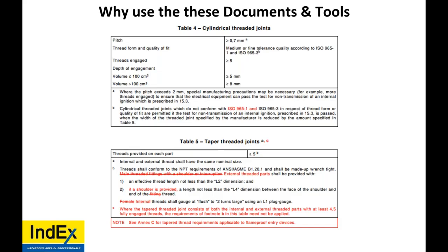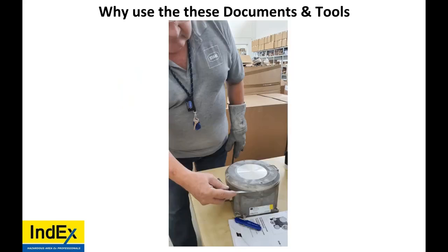If you don't tighten all the bolts correctly, if they're too loose, that's a problem. If it's too tight, you can damage the walls of the cover of the enclosure. You can warp it. This is a bomb-proof safe. We're using the feeler gauge there to make sure that the cover on this threaded type enclosure is sufficiently tight. Now, during a close inspection, if you're not using a feeler gauge, you're not doing a close inspection. You're not doing a legitimate close inspection.